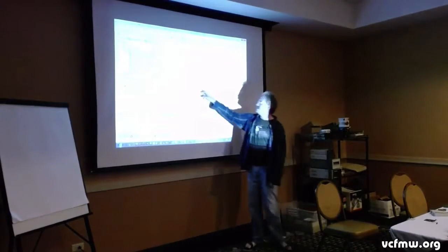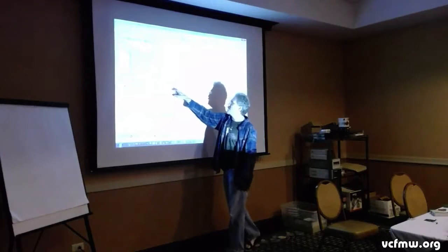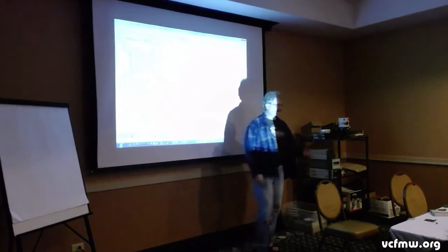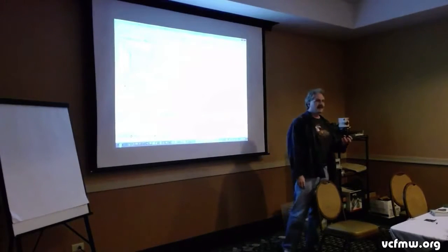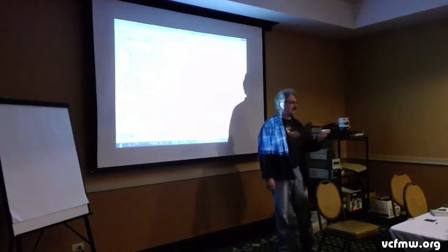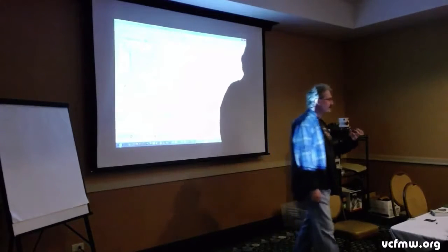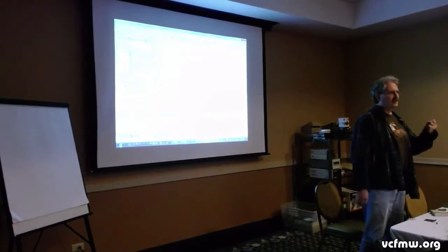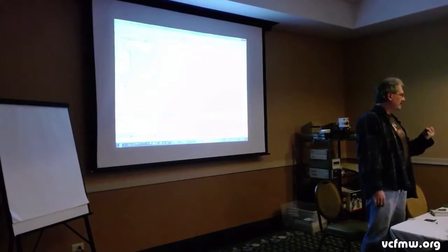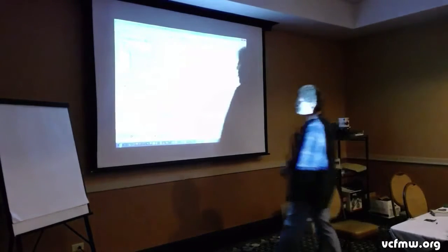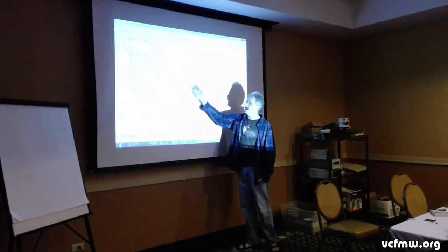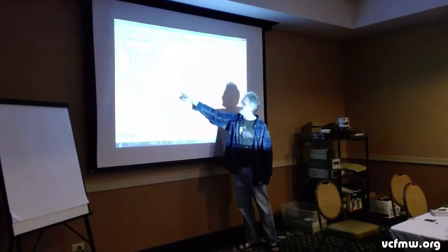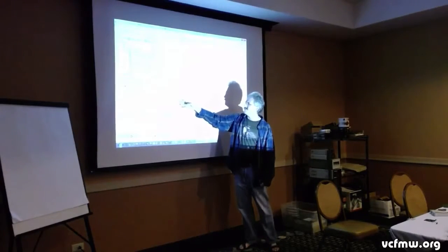But this is the real trick of using non-combinatorial logic here. As you can see, this is a special kind of notation. Basically what it's saying is I want you to actually create some flip-flops, right? At the end of the day, I want you to create some latches or flip-flops, and I want you to be able to store some data inside the system. So it's not just combinatorial logic, it's something that's going to hold its state when I get done. The nice thing about this is we've got a negative edge clock here and a positive edge reset. And as you can see, the code is very, very simple.